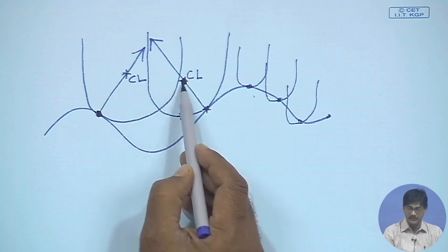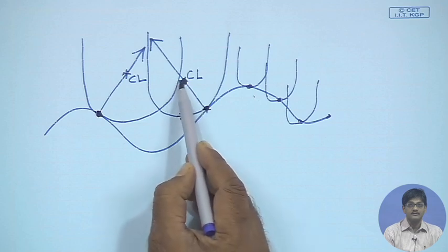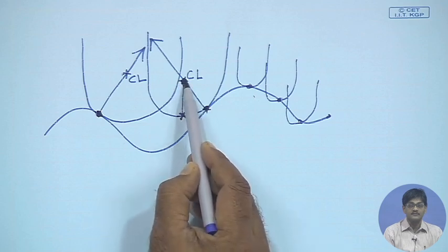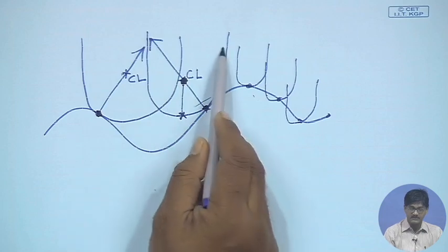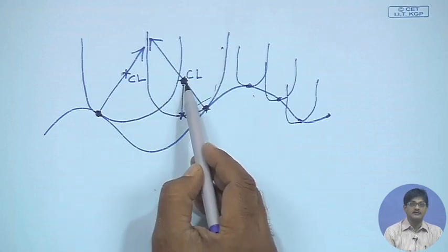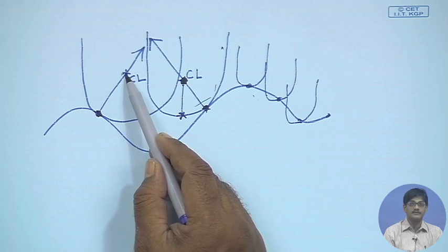It is completely in contact with the surface at the cutter contact point, and this is the location of its central position of the spherical end to fix it in space. So, cutter location points are the ones which should be given to the machine control.